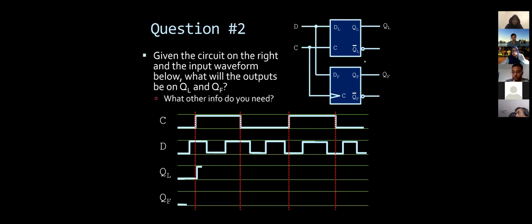So what happens next is when the timer goes up. If it happens that D at this moment was also high, then QL goes up because it's positively triggered. And then if the signal D goes down, this also goes down. And then if D goes up, this one also goes up. But later on, you see here, if we go into this state when C is low, this one is just always high. And it's repeated again. So you see how it changes over time, what shape it has.